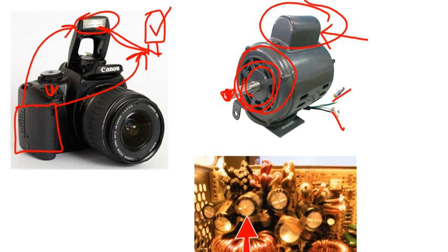What that does is, when you first turn on this motor, the energy actually goes to the capacitor, charges the capacitor, and then it sends all of that into the motor, causing it to have a really strong initial rotation, which allows the motor to begin rotating. And once it begins rotating, it doesn't take too much more work in order for it to keep rotating. This is also how a lot of refrigerators and freezers work with their compressors. The compressors are always under a load, under pressure, and so you use a starting capacitor to get it started, and then it can keep going.